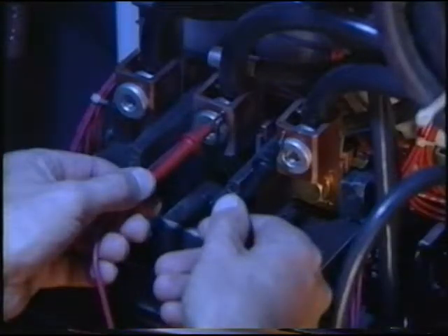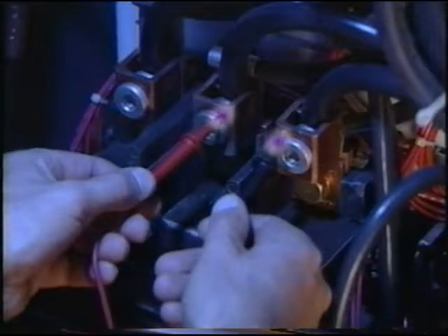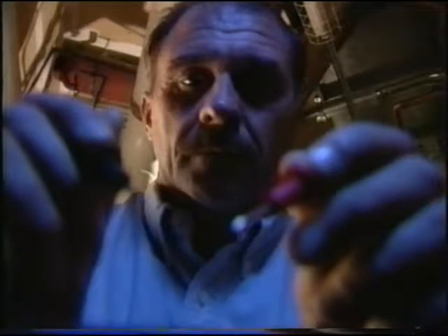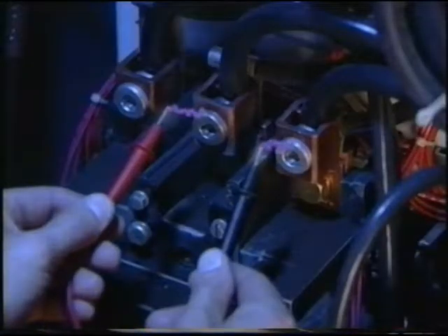At these current levels, the tips of test leads superheat, and the handheld probe tips start to burn away, drawing an arc from the contact point to the probe tip. The tech sees a bright blue arc flash and at the same time is startled by the bang of the arc exploding inside the meter. The arcs follow the vaporized test probes.